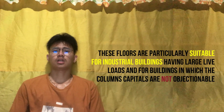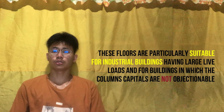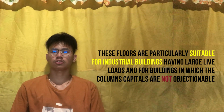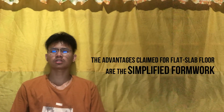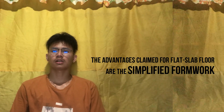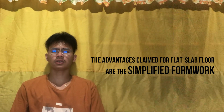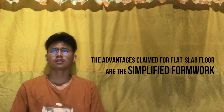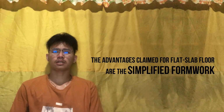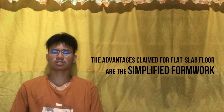These floors are particularly suitable for industrial buildings having large loads and for buildings in which the column capitals are not objectionable. Among the advantages claimed for a flat slab floor are the simplified formwork, better lighting due to the absence of beams and girders, a saving in height for a given clerestory height, a uniform surface for suspending sprinkler systems, piping and shafting, and, because of the absence of sharp corners, better resistance to fire.